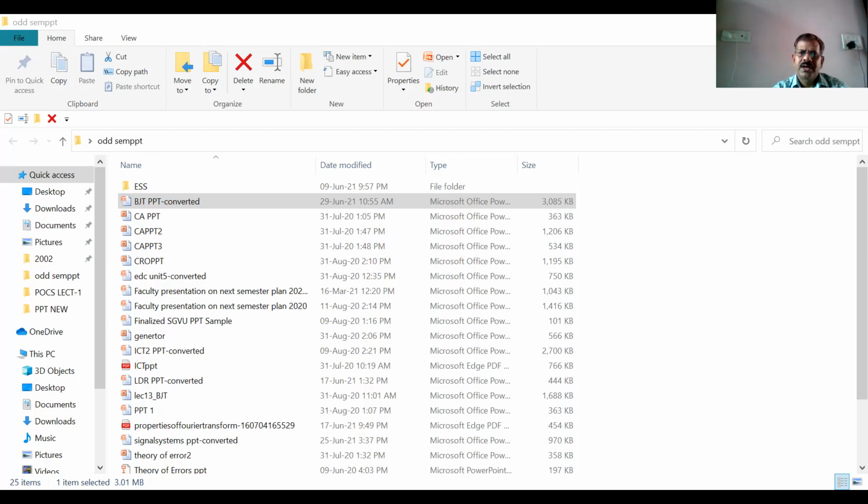Next, transistor operating modes. The first one is the active mode. In active mode, the base emitter junction is forward bias and the base collector junction is reverse bias. Second is the saturation mode. In saturation mode, the base emitter junction is forward and the base collector junction is, sorry, also forward in saturation mode. So in saturation mode, both junctions J1 and J2 are forward bias.